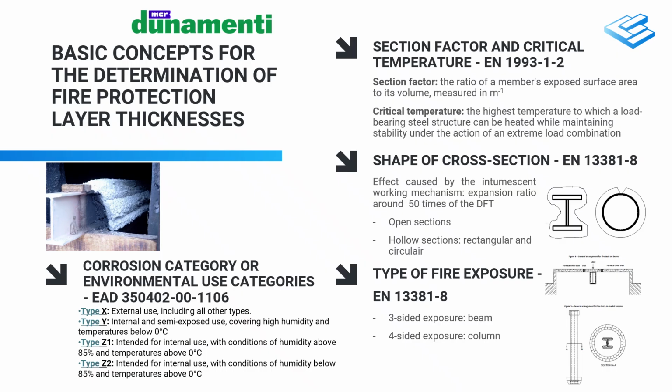This value is expressed as a ratio which divides the perimeter of the section exposed to fire by the cross-sectional area that heats up. The higher the value of this ratio, the thinner the section's walls, and the greater the thermal insulation required to prevent heating. So this will be a key aspect of a cost-effective fire protection solution.